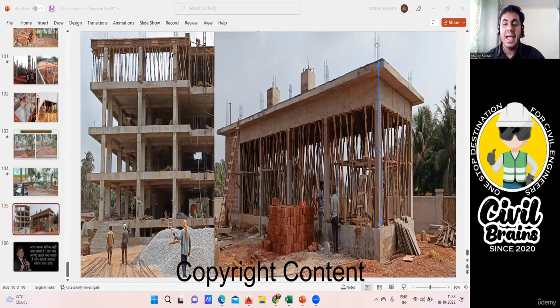Actually, you should not take the complete height. Like I mentioned in one of my earlier courses, whenever you do column concreting or column calculation, the common practice is that you cast the column till the bottom of the beam. You can see this is your beam. Only up to here I'm going to cast my column first, and then I'm going to put my beam bottom. Then this beam will be cast, and along with the beam, your slab will also be cast. And finally, whatever portion you had missed, this final portion, I'll show you in a different color. From here we calculated, but again my column will actually go from here to here. This height will come along with your beam and slab concreting.